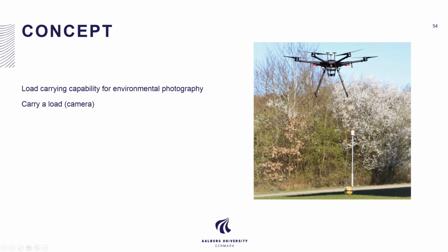Here is one of our Matrice 600 Pro that I am flying to test the physics of the system, just to get an understanding. Inside of the ball, we had an accelerometer, gyroscope, magnetometer, so a full IMU system that we are recording the data from to figure out how the system is actually performing, what the dynamics are, and so on. So we wanted to test this outside with a huge drone before putting it into our Quanser system.